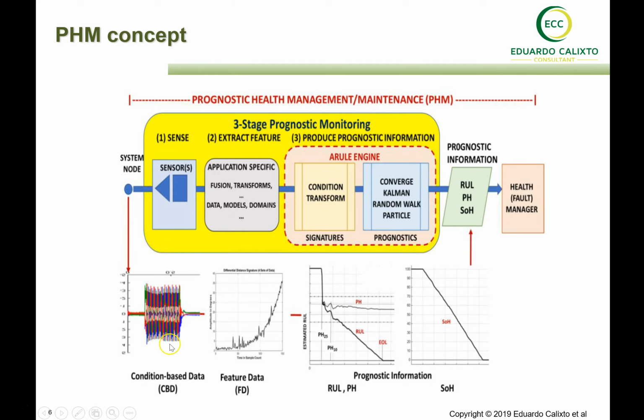So here we can see the condition data that comes out. These data are normalized. Then the prognostic information, remaining useful life, based on time and on different input information that can be temperature, pressure, voltage, rotation, or vibration, for example, will be demonstrated in a picture on a screen, as well as the state of health of the equipment based on the condition.